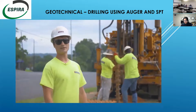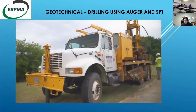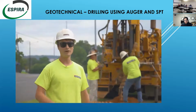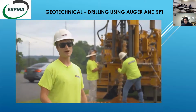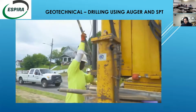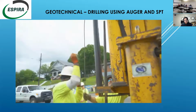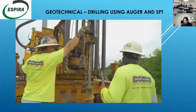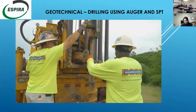So this rig is a CME 75, and what we have are hollow stem augers. They're hollow in the middle, so we drill down to the depth we desire, and then we put a rod in it, a spoon, it's called a split spoon, and we put the hammer on top of it and count how many blows per 6 inches, and we come up with the end number from that.